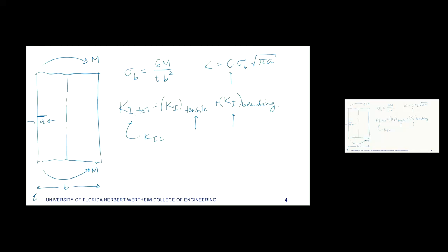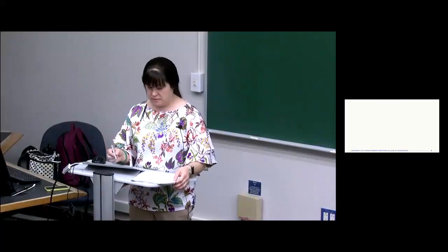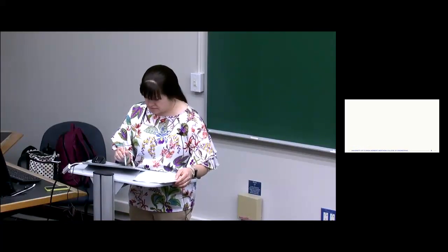The last thing I wanted to mention is another really common situation, which is a crack emanating from a hole in a plate, okay, in biaxial tension. Because this is like every riveted joint or bolt hole through a plate or something like that. So here's a situation